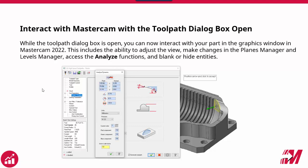Here's another cool one. We now have the ability to analyze our model even when we're in a toolpath. So even if I have this toolpath page open here and I'm working on my raster toolpath, it looks like, let's say I wanted to make sure the tool I'm using has the right radius for what I'm trying to cut. I can go in here and I can dynamically analyze any of these features. I can use analyze entity, any of those analyze functions to analyze my model, even when my toolpath is up on my screen.